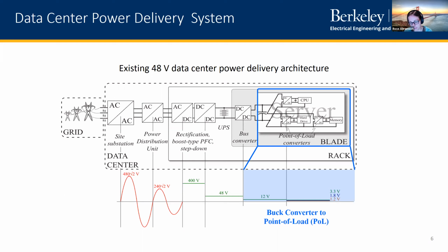And so these types of topologies can be things like multi-phase buck converters, or other existing converters that are already on the market by industry. And so combining this first stage hybrid switch capacitor or fixed ratio converter with a second stage buck converter is a very common method for getting from your 48 volts down to your point of load.